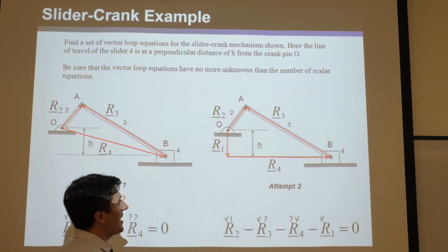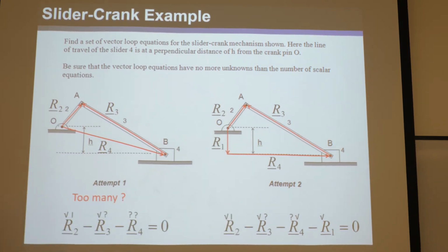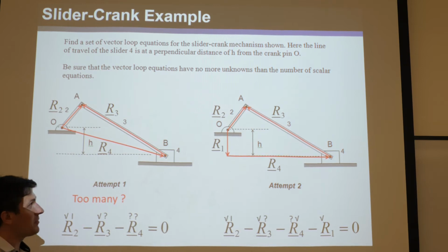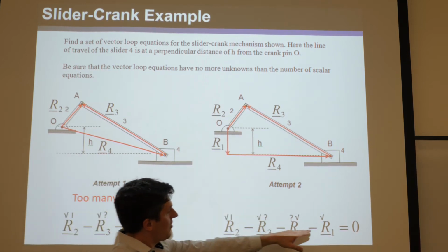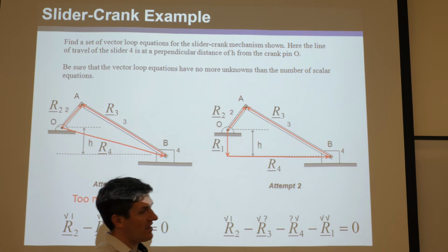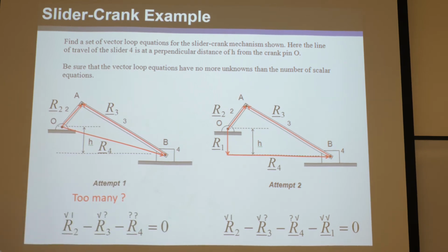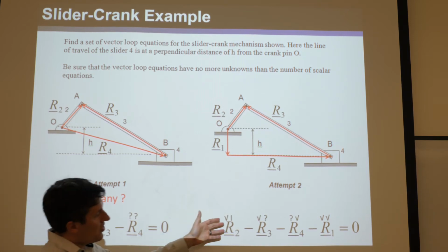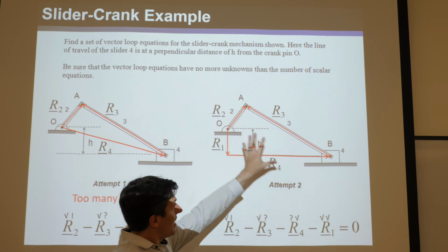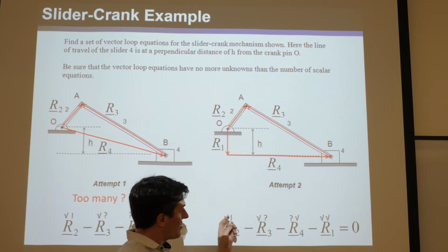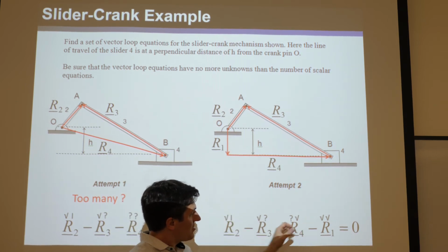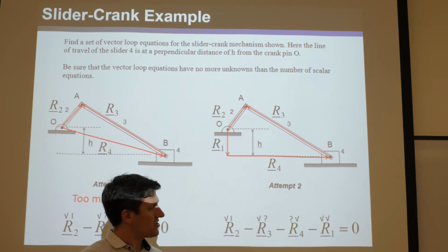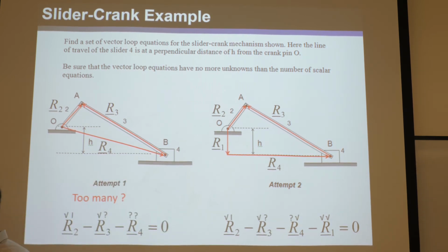So it's 3 pi divided by 2. Always use radians, or you'll get really messed up. So check, it's 3 pi divided by 2. That's the angle of R1, and it's never going to change, so that's why you know it. Okay? So aha, we now have a new vector loop equation that is true and works, and we follow the convention. Again, it's 2 equations, and fortunately just 2 unknowns, so it can be solved.